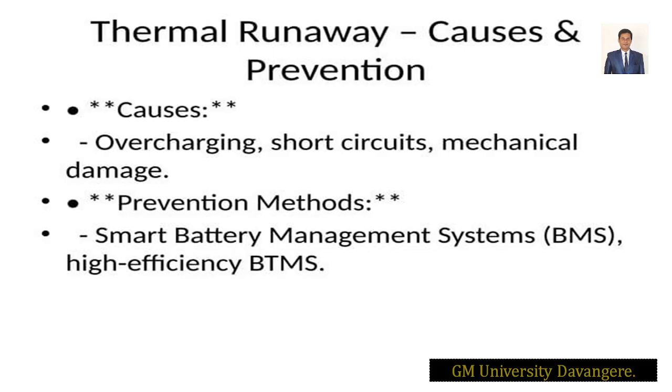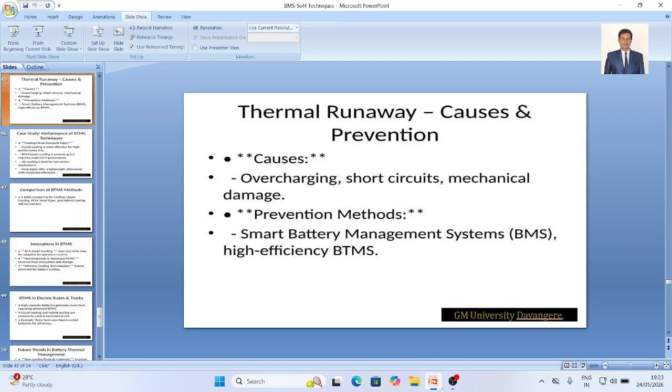Due to a short circuit also it may happen. Due to mechanical damage in the cells also it may happen. That is, we are just talking about the electrodes of the cells, right? And also due to the short circuit condition, due to the overcharging. These are various possibilities for the battery to get degraded, and because of the thermal runaway, these are the causes for the battery to decrease its lifespan.